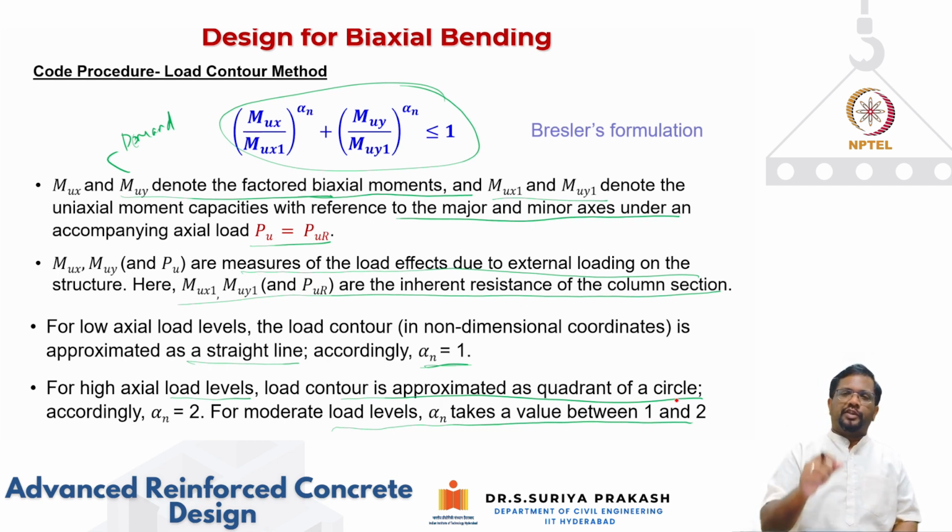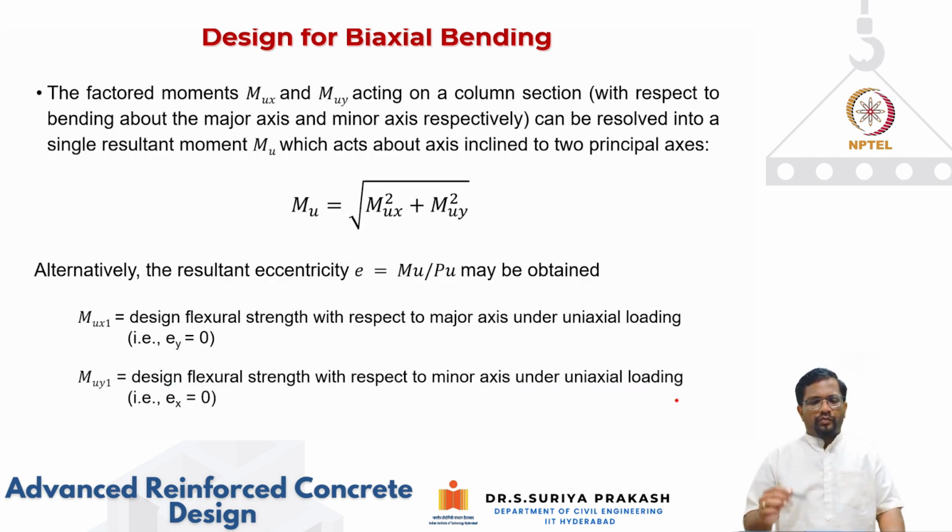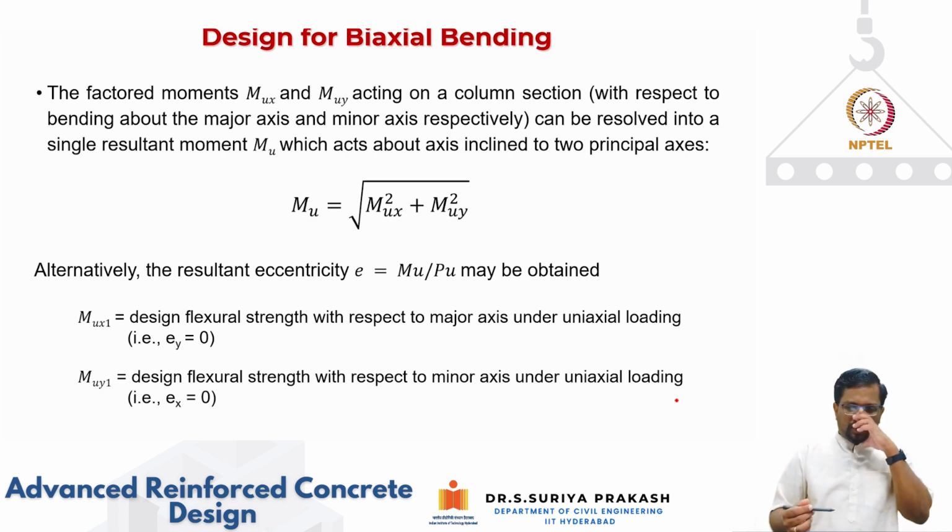But for design purposes, what we can do is use this load contour method to quickly see for biaxial bending whether the chosen dimensions and chosen reinforcement configuration are satisfying the requirement or not, right? Okay. Now, let's see what the design process is.